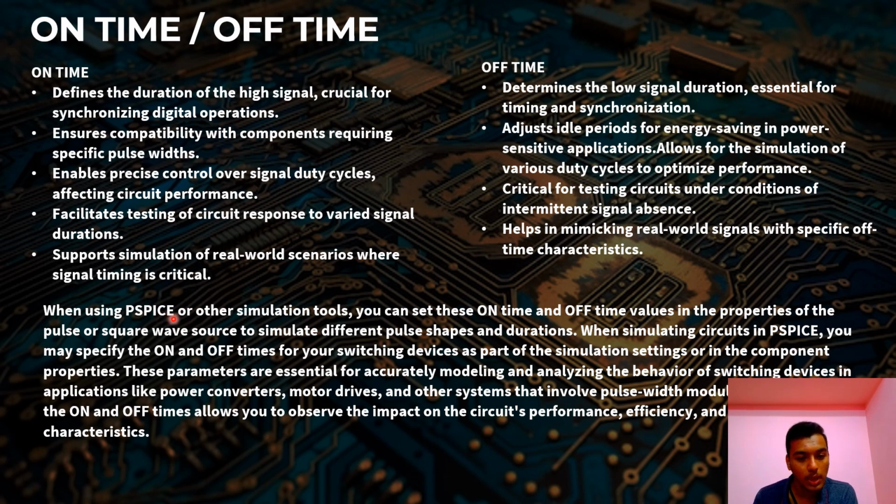When using PSpice or other simulation tools, you can set these on time and off time values in the properties of the pulse or square waveforms to simulate different pulse shapes and durations. When simulating a circuit in PSpice, you may specify the on or off time for your switching devices as part of the simulation settings in the component properties.